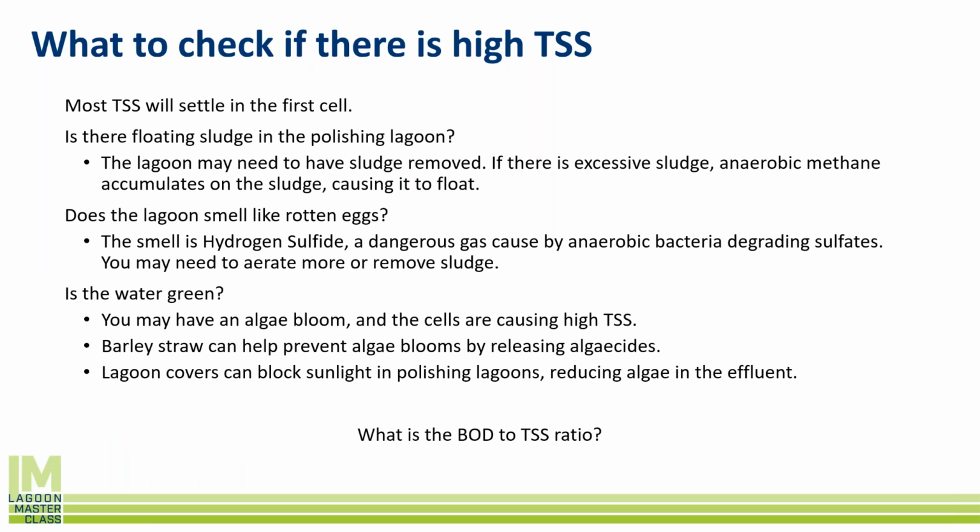Sometimes at the same time as the methane causing the bubbles, you might smell some rotten egg smell. That's hydrogen sulfide. That's a pretty dangerous gas. That's why we don't like to go in confined spaces, because at very low concentrations, it can cause you to pass out and it can actually kill you. That's also caused by anaerobic bacteria who are degrading sulfates.